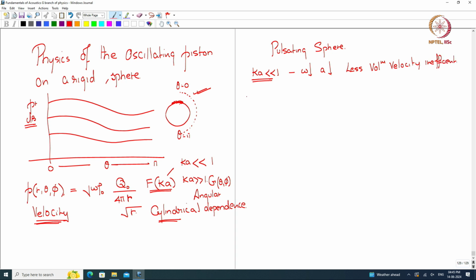So now if you look at the acoustical impedance on the surface, it is dominantly imaginary, not purely imaginary. We made some approximations. So there will be a j times some component which will dominate, but a small real component is there, which accounts for the radiation, however inefficient it may be.